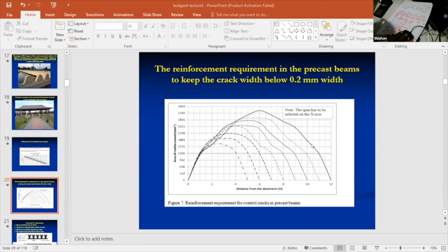So when you have reinforced concrete structures like this, the first thing we do is optimize the structure, and then we analyze the structure, get bending moments and shear forces, and then find the reinforcement needed in the beams and slabs. So that is the design method. To find the reinforcement in the beams and slabs, you can make use of the examples that we have just discussed. In that one, I showed you how to find the reinforcement when the section is known. So any questions on this?